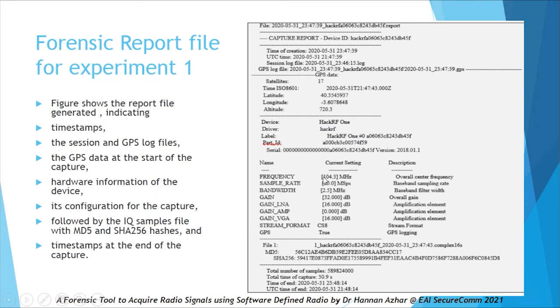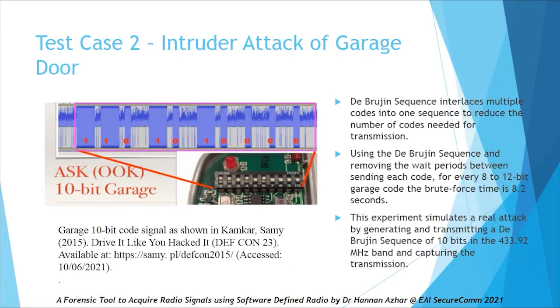So what we did was basically we simulated this experiment using a transmitter and receiver. In this case, the HackRF, and the other one is the RTL-SDR, which is capable of receiving from 25 megahertz to 1750 megahertz, with an internal oscillator and aluminum enclosure as well to reduce noise. There's another antenna here as well, which we used as the receiving antenna. This is the transmitting antenna.